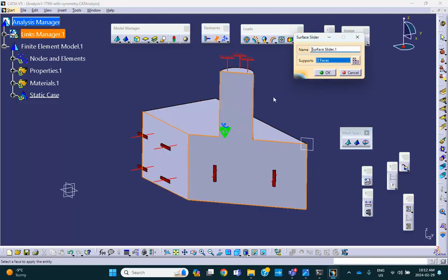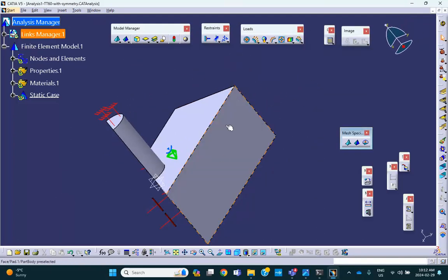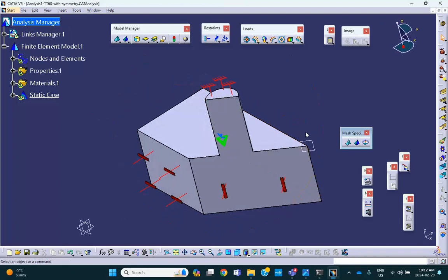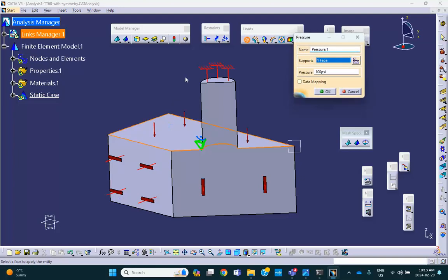Very frequently people forget to put rollers there, or they put them on the wrong spots. But anyway, you're doing this because you don't want to make a mistake. Anyway, let's save everything. Oh, the pressure. Let me apply the pressure here. Should I divide the pressure by 8 because the top is actually 1/8 of the original surface? The answer is no. Pressure you don't divide.